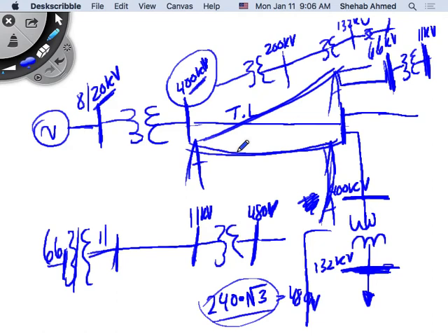So anywhere there's electrical equipment inside will be called a substation. Okay? And typically what you will have there is nothing but an incoming feeder. This is the terminology the power system guys use, right? So it's an incoming feeder, and you will have a bus bar, and then you will have a transformer, and then a bus bar, and then an outgoing feeder. In addition to that, you will have all the protection equipment and communication equipment that go along with that.